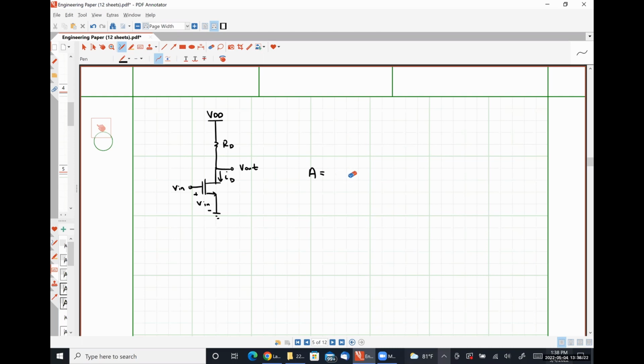Actually, a better way to put this. Our open loop gain in this system is gm. What I mean by that is the ability of the transistor to convert the input signal voltage at the input to a current at the output. Then our sense mechanism is this resistor RD. Because the current's flowing effectively the wrong direction in a small signal sense, our overall system gain looks like negative gm RD. So our open loop gain in this case is gm, if we're looking at this from an open loop amplifier perspective, and our sense mechanism is that resistance RD.